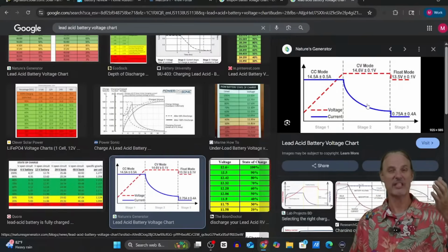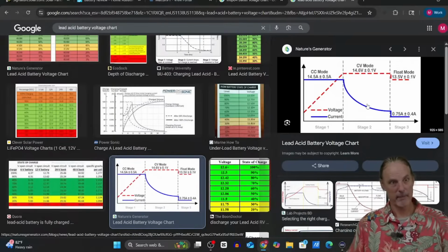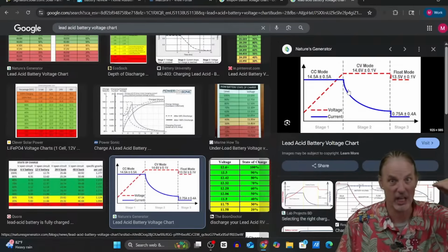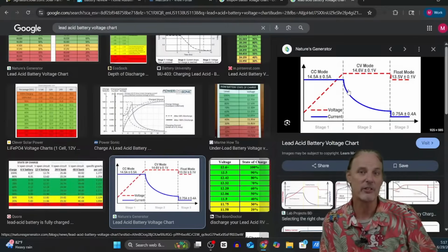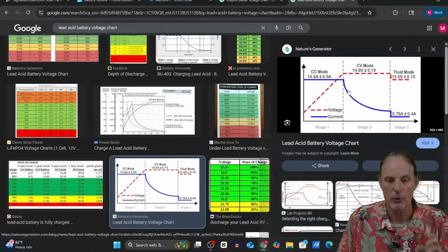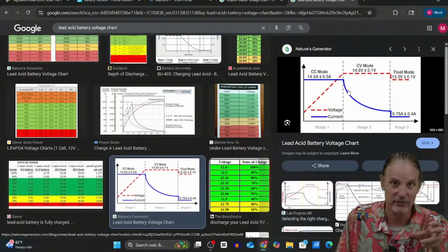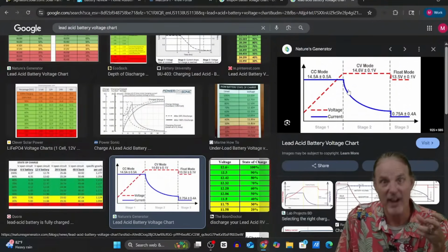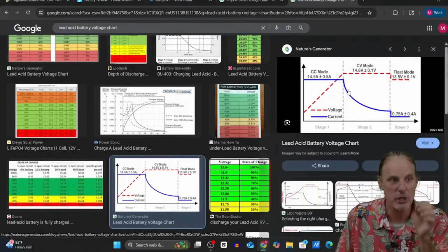And that is why you'll see in a lot of these devices where you have these lithium drop-ins, where the state of charge is useless afterwards, because the lithium battery gets to this 3.2 range here in the middle and then just stays for 80% of the life of the battery. So you drop in a lithium iron phosphate battery into your lead acid, and the state of charge of your lead acid reports that it's sitting at 80%, 80%, 80%, 80%, 5%. And you're like, whoa, what happened? Well, that's what happened, because it's measuring the voltage.